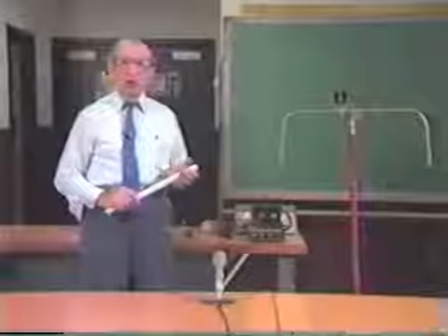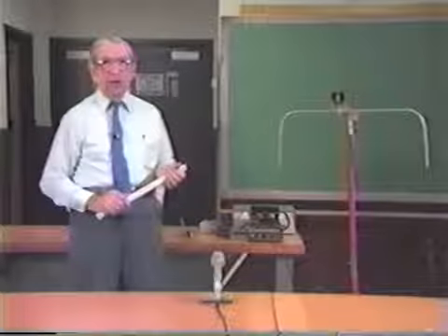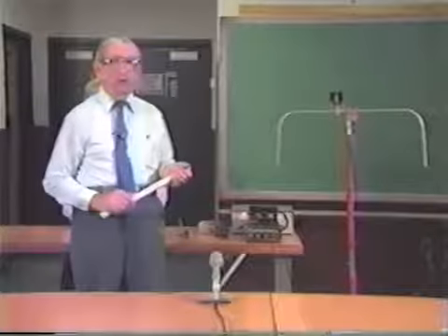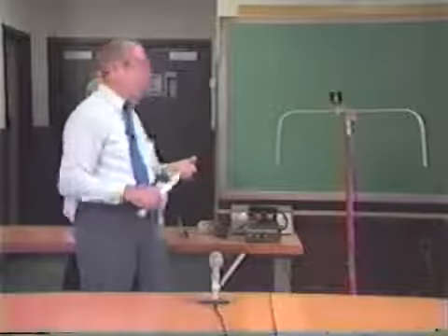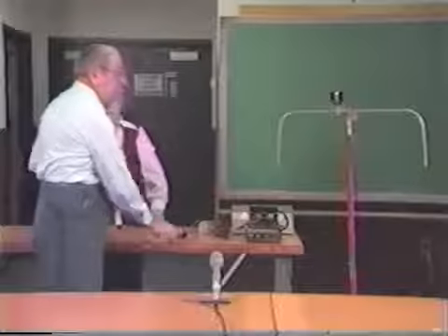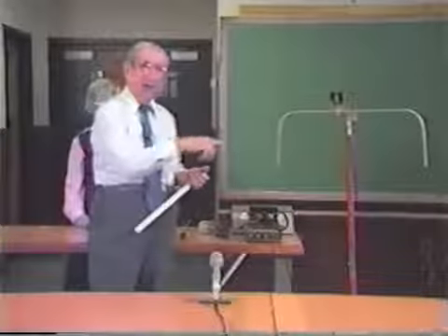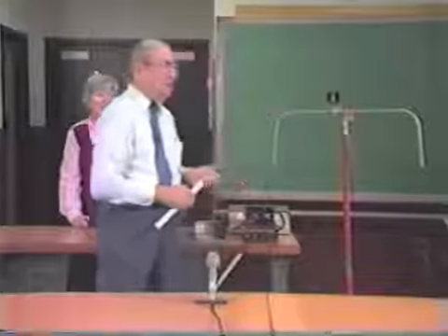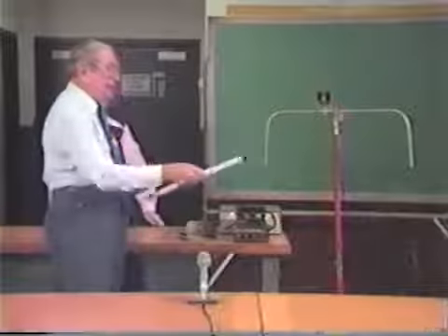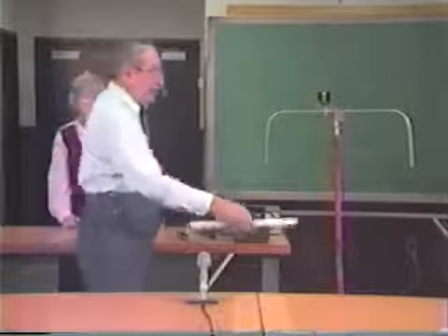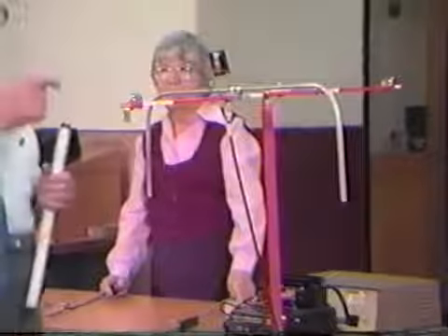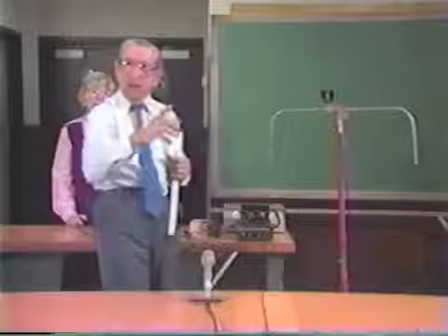I wanted to show you also, while I'm in the dipole area, the polarization of the antenna. If you remember, on the dipole antenna when it was horizontally polarized, I was able to demonstrate the polarization. Now, I have an antenna here that's a half-wavelength long. It's 38 inches long, but I bent the ends down for a specific purpose. I wanted you to see that this antenna still has its voltage loops at the end and the current loop at the center, so that our electrical field is in the center where the current is, and the electrical field is the one that sends out the radio waves.